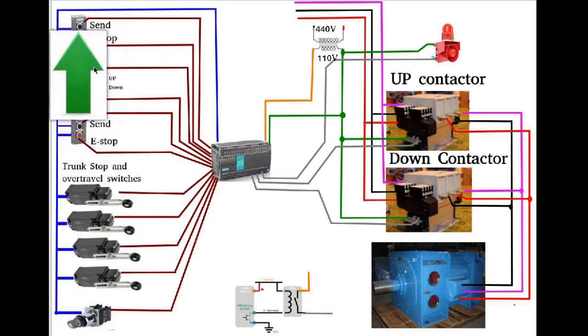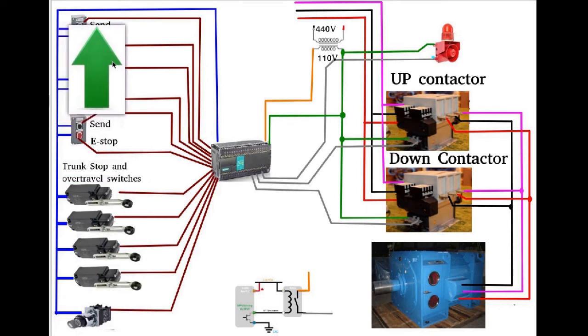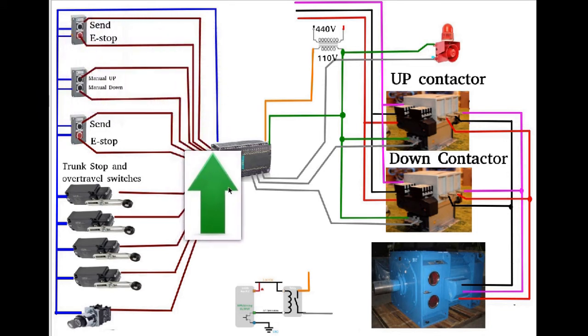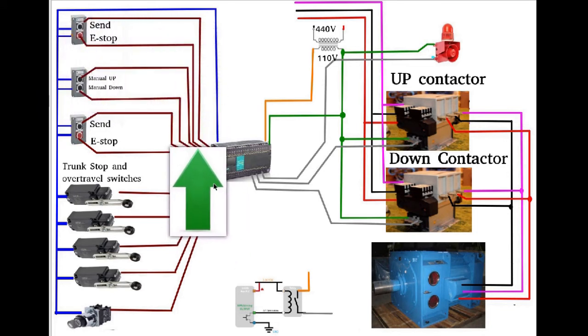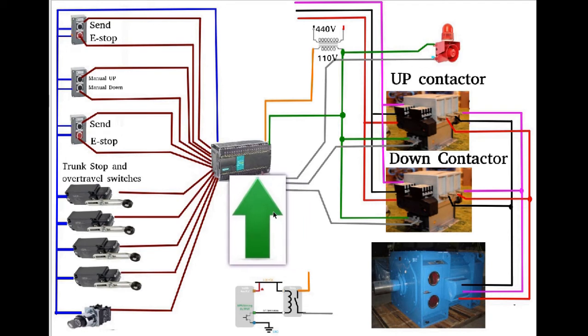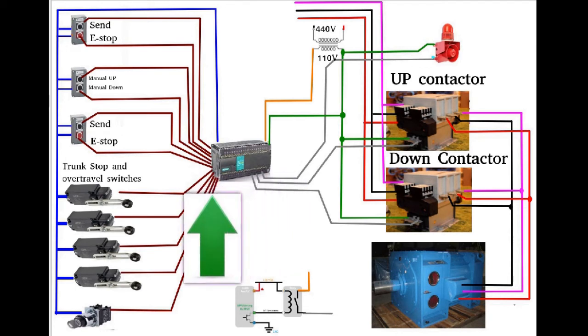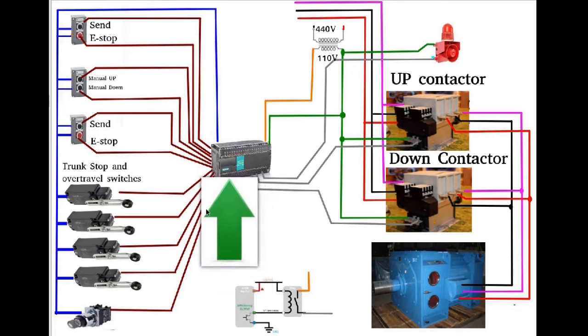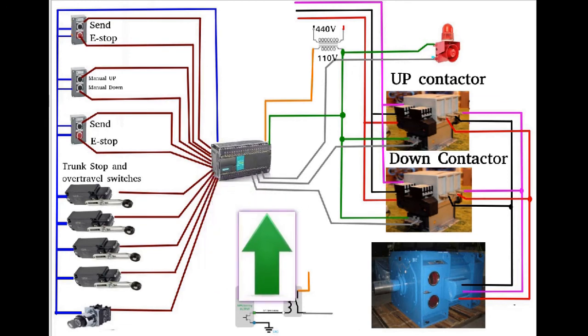So whenever somebody presses a switch, really what is happening is bridging the 24 volts positive into this connection over here, taking it to the PLC. I drew them to the back of it, but in reality this would be more like the inputs. These screws over here are the inputs, and this over here will be the outputs. But trust me, it's a much cleaner way how I drew it right now.